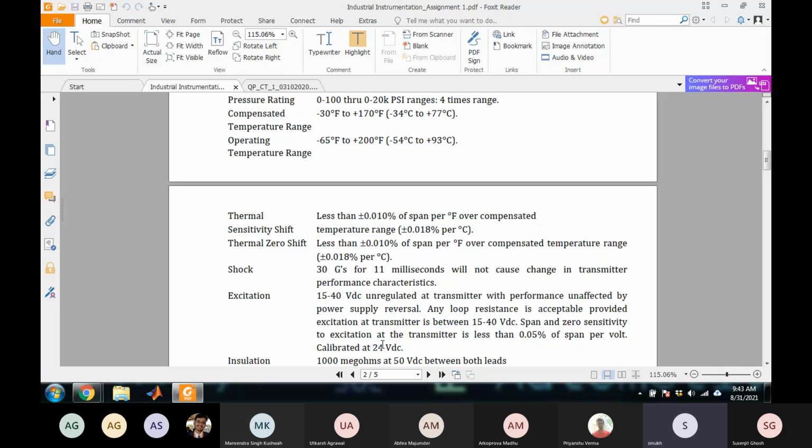Once you understand the terms, it is just arithmetic with the calculator, but you need to interpret the terms. That's what we have tried to impress upon you in this class: how to interpret the data, so that you can decide whether to buy an adjustment, what kind of error can happen, whether you should go for temperature compensation. How do you assess that from a given data sheet of a commercially available sensor? That's what we are trying to show you.